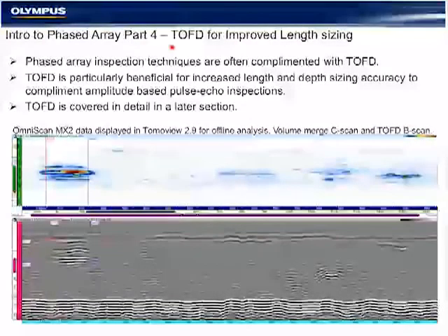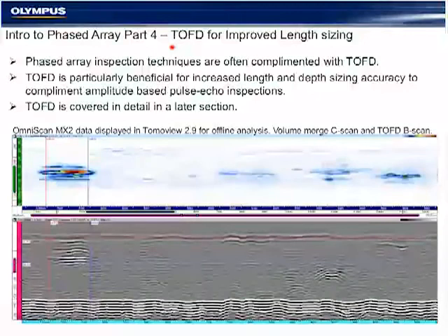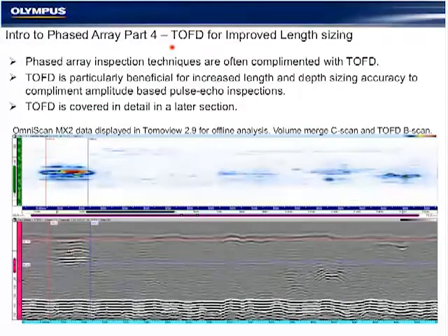And we get asked often, why do we use TOFD with phased array? There's generally two reasons. The overwhelming majority of our 30-degree weld bevels can be inspected without TOFD. But when the weld bevel becomes more narrow at unfavorable perpendicular angles to the inspection beam, for instance, a 60-degree beam would be optimum for inspecting a 30-degree weld bevel because it creates a perpendicular inspection interface for the bevel where most flaws occur. So we supplement that with TOFD.